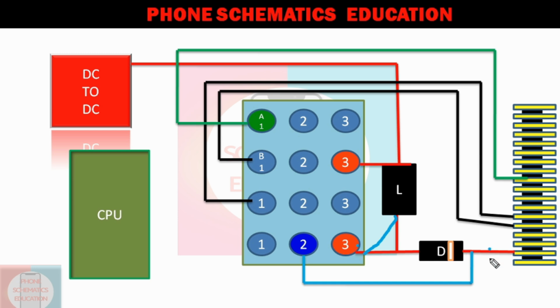Now you get a diode value here. This diode value also belongs to the IC because this IC is connected on both sides from the coil for switching. That's why. Now how to confirm whether these two pins are connected to each other or not?